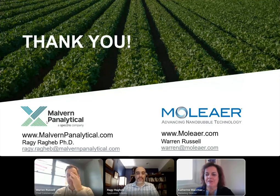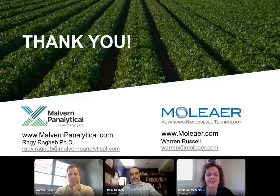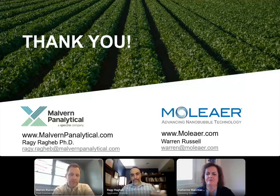What is the concentration of bubbles, particles per volume, that you're able to reach, Warren? So concentration is relative to two principal things. One is the constituents in the water, which can significantly change the concentration accumulation that one can achieve. Also the methodology. If we're recirculating, for example, typical irrigation water, achieving hundreds of millions of bubbles per milliliter is a common metric that we work towards.